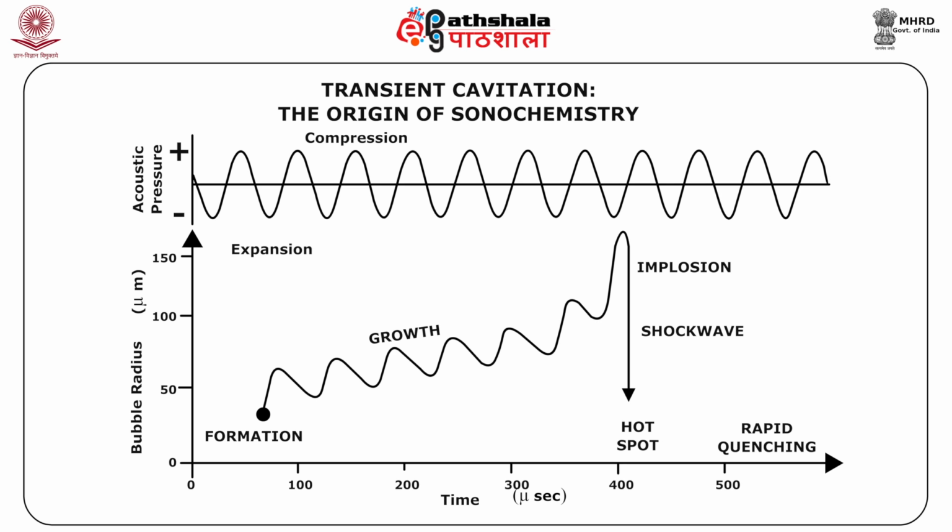position. When the negative pressure caused by an ultrasonic wave crossing a liquid is large enough, the distance between the molecules of the liquid exceeds the minimum molecular distance required to hold the liquid intact, and then the liquid breaks down and voids are created. These voids are the so-called cavitation bubbles.